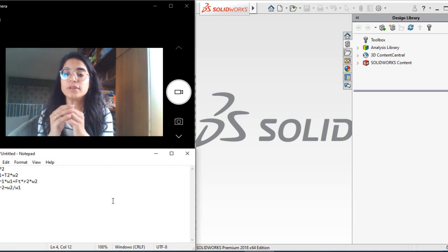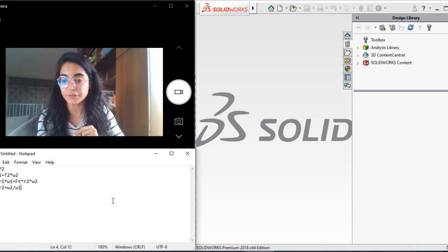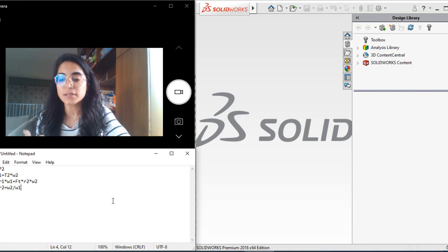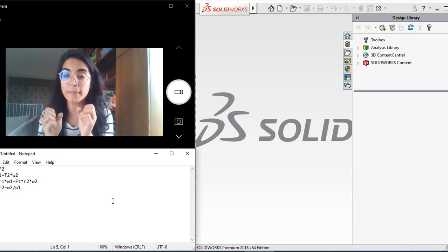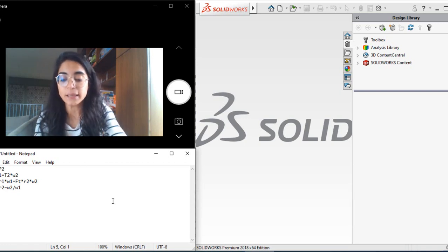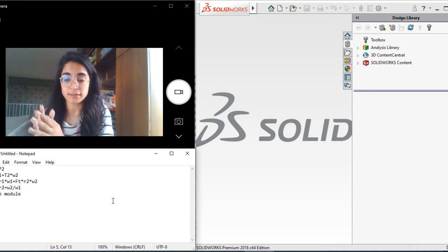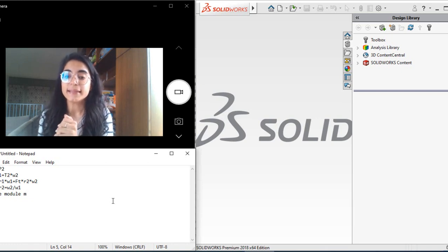And that's why, guys, there is a small gear called the pinion that has the highest angular velocity, and the largest gear, called the gear, has the lowest angular velocity. Not only this, guys, we know that if we have two meshing gears, we should have the same module in SI unit. In English unit, it is called the same transversal pitch.